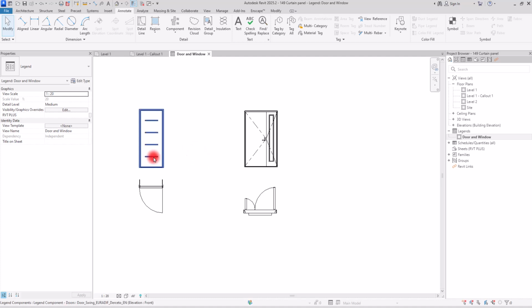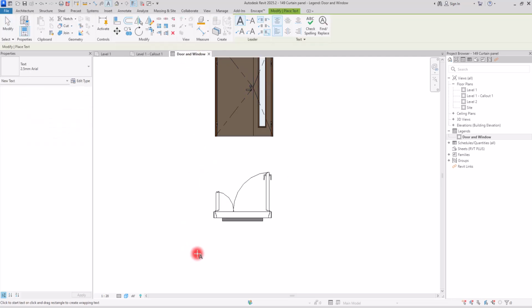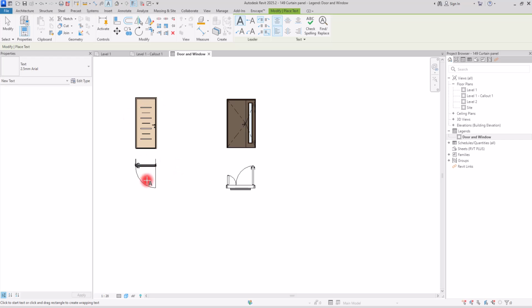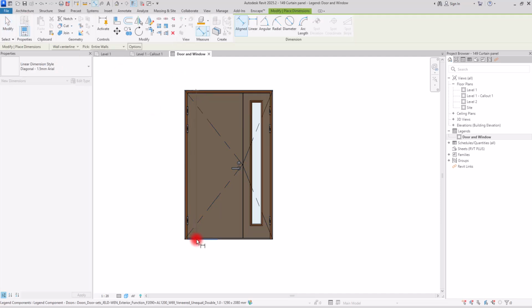After you add all of them, you can go to the graphics section. You can put this part on consistent color. You can put this section on font. And then under this part, you can create a text. In this section, you can add the information about that door, about the opening side, about the type of that door, about the color, about the material that you used for that, and this way you can complete this part for this section. If you want, you can also create a table and put all of these in that section, and you can add the size of your door, for example this way to this part, and then like this to here. And after that, you can add information about the smaller sections too, like this, even smaller parts